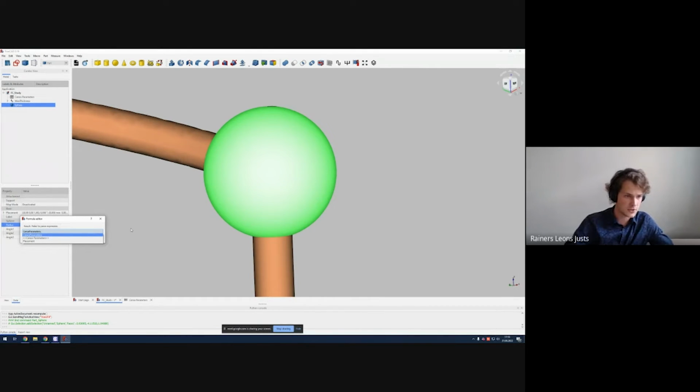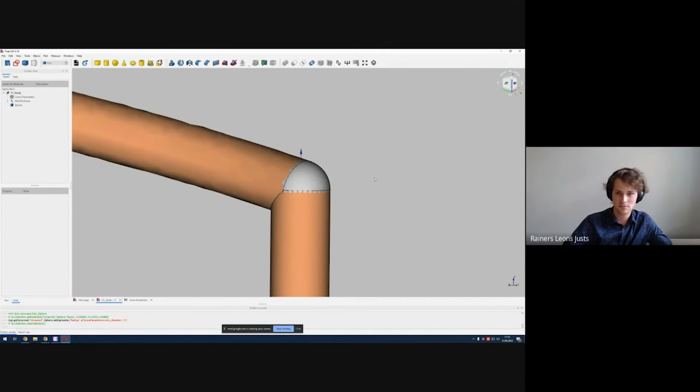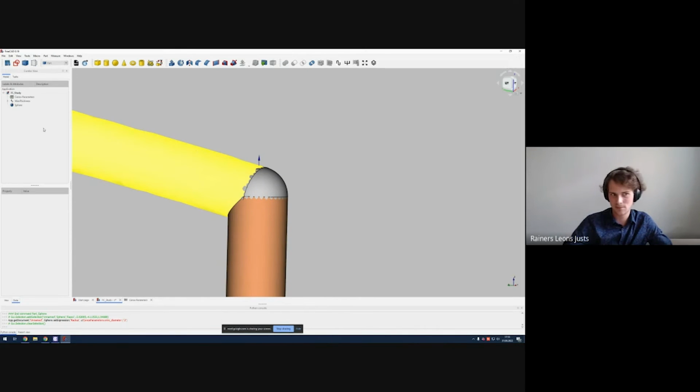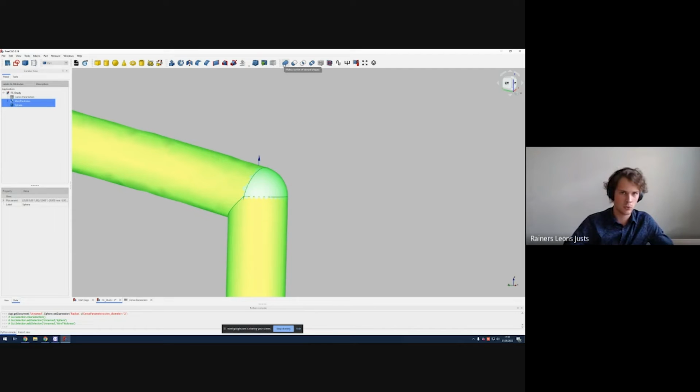So let's call CENOS parameters, wire diameter. And since we need the radius, we're going to be dividing that by 2. And as you can see, we have created a sort of smooth solder joint. So let's combine these objects into a single one using the Boolean operation called fusion, union.